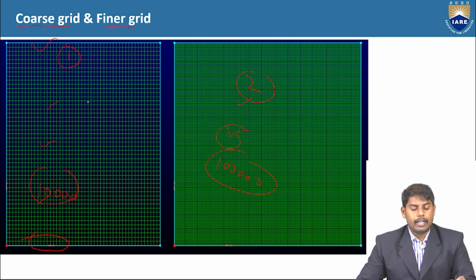So it's not that you have to use a finer grid every time, or a coarser grid every time. Let's say you have flow over a flat plate and you have experimental results. Let's say the velocity is 1.45, which comes from the experimental result. You have to perform the meshing for different grids. Let's say initially use 10,000, then double it to 20,000, and next go to 30,000.